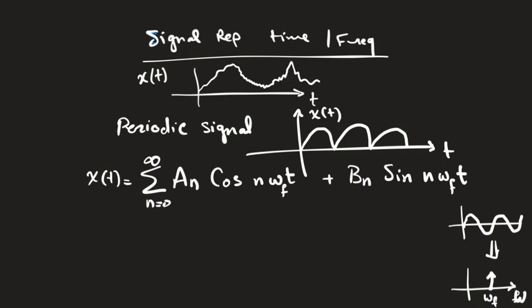So basically this one is a sinusoid with certain amplitude, added to it another sinusoid, double frequency, with another amplitude, added to it another sinusoid, triple frequency, with another amplitude, and so on, right? Now when we look at those in frequency, it becomes one here, one next, one next, one next, one next, right? So now we have been able to look at this periodic signal from a frequency domain perspective and see which frequencies it occupies, right?